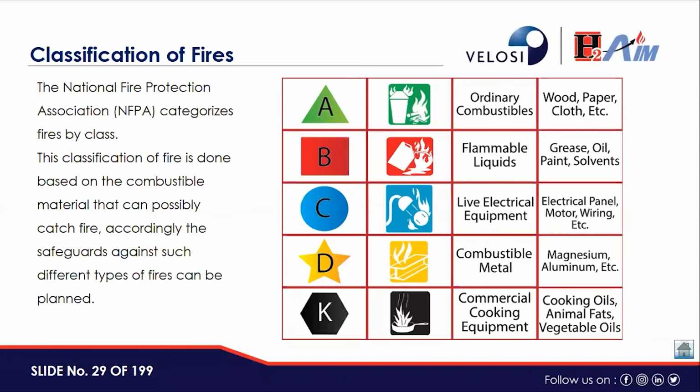So basically, these electrical fires require non-conductive material to extinguish a flame, so water alone is not a good solution for this type of fire. Facilities with sensitive equipment may prefer clean agent suppression because it won't leave residue or damage electrical equipment.